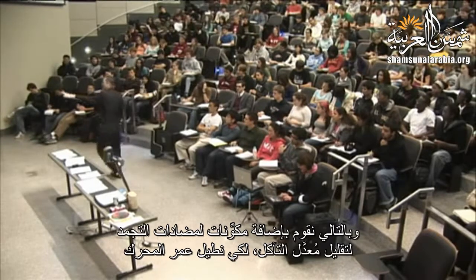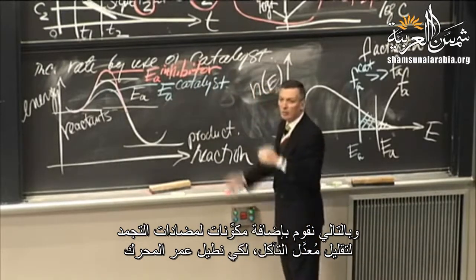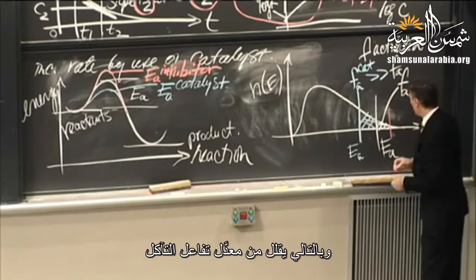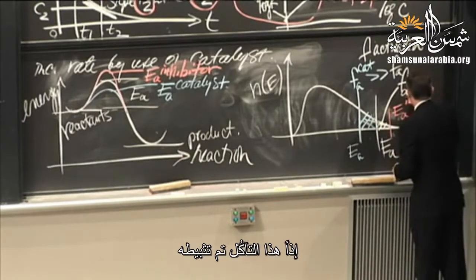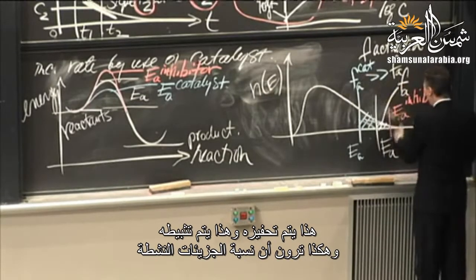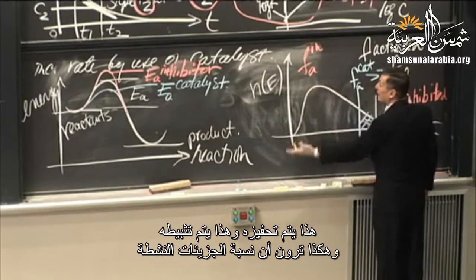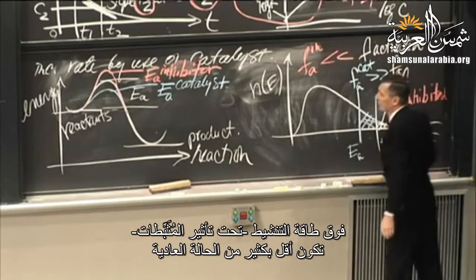And so we add components to the antifreeze to reduce the rate of corrosion, to lengthen the service lifetime of the vehicle. And so what does the inhibitor do? It raises the activation barrier for the corrosion reaction and thereby reduces its rate of reaction substantially. So this is inhibited. Okay, so this is catalyzed, this is inhibited, and you can see that the fraction of active species over the activation barrier under the influence of inhibition is much less than the fraction otherwise.